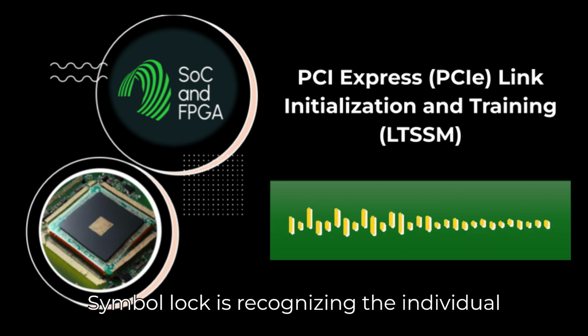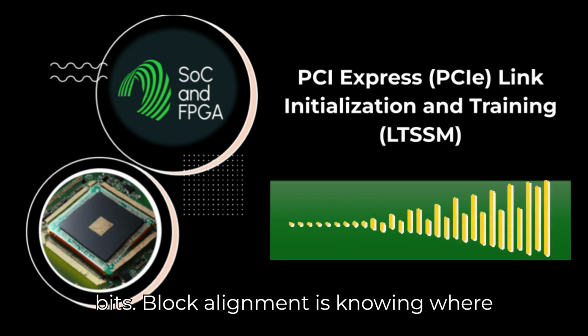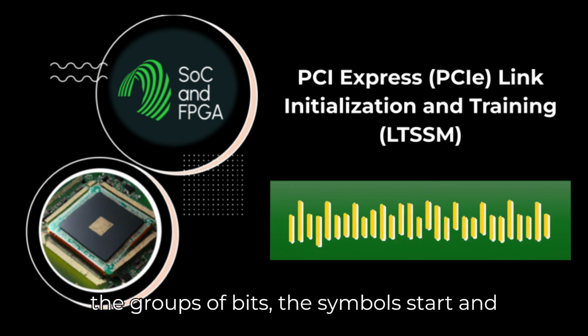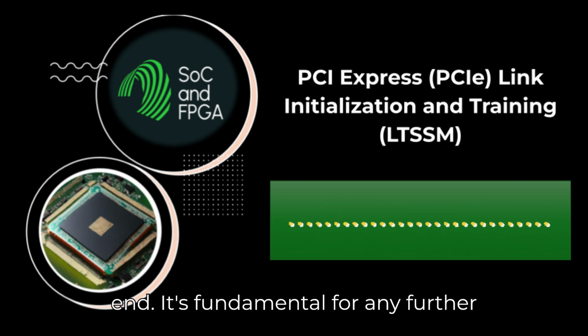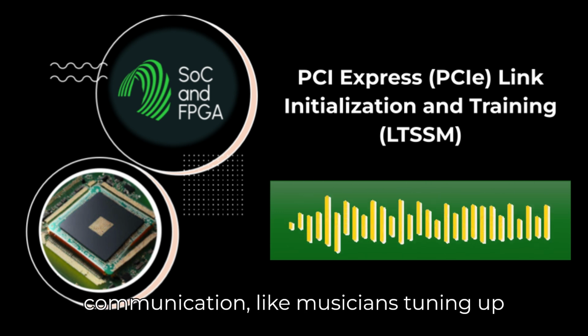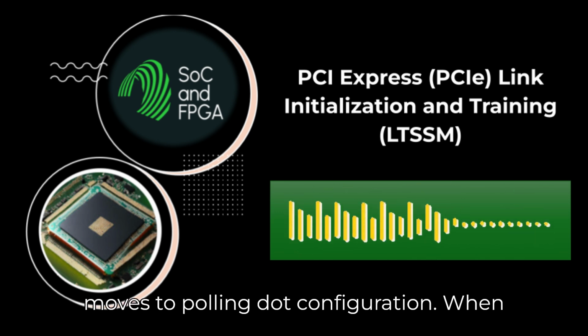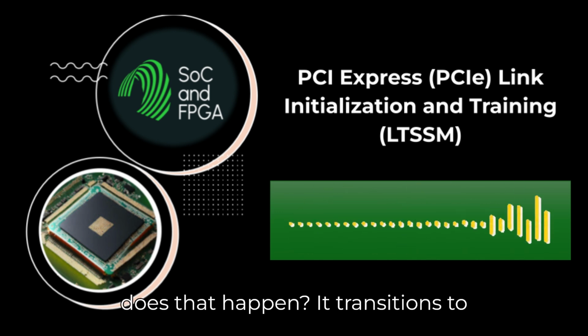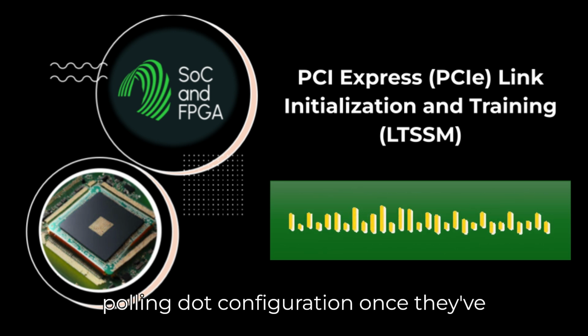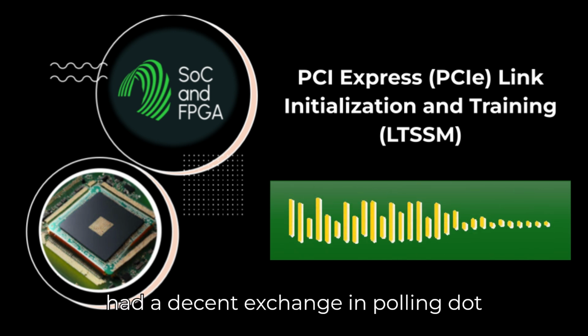Exactly. Symbol lock is recognizing the individual bits. Block alignment is knowing where the groups of bits, the symbols, start and end. It's fundamental for any further communication, like musicians tuning up and finding the beat. Okay. And then it moves to Polling.Configuration. When does that happen? It transitions to Polling.Configuration once they've had a decent exchange in Polling.Active.